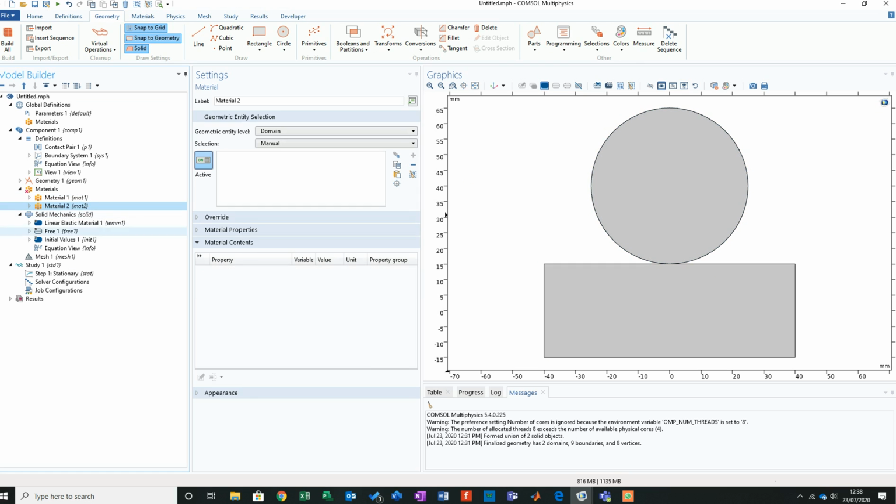And I come back, and now if I go back on and choose that, it instantly says, right, you've done that. Now populate what you need. So what we'd said is that E2 was going to be our Young's modulus for the second material. V2 again, and D2 again for the second material. So now we've got the two materials interfacing. You'll know that there's no marking, no complaining, so it means everything that's in there is good.